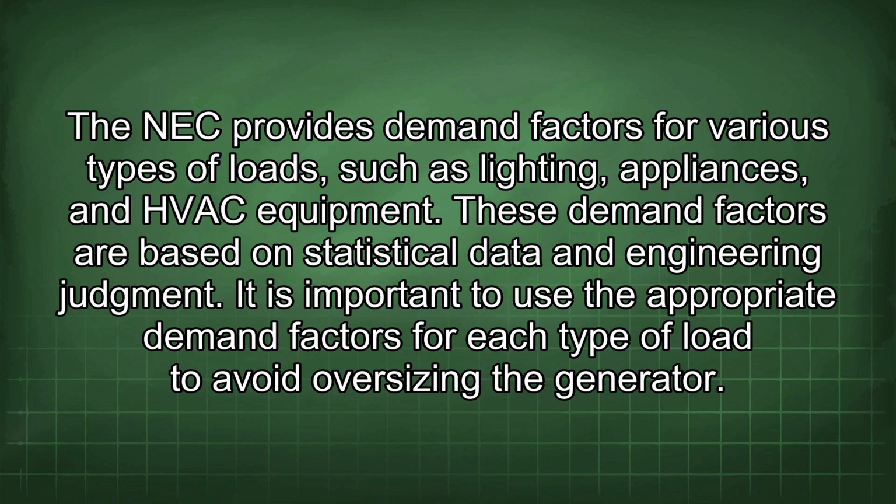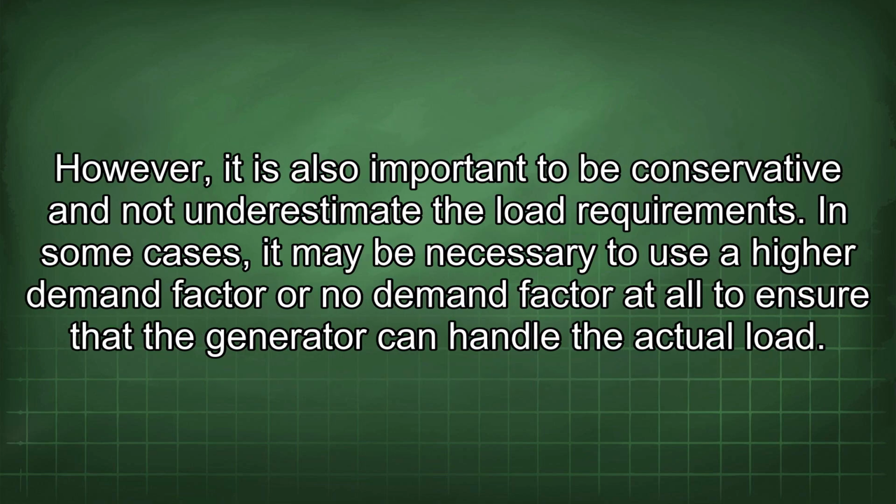It is important to use the appropriate demand factors for each type of load to avoid oversizing the generator. However, it is also important to be conservative and not underestimate the load requirement. In some cases, it may be necessary to use a higher demand factor or no demand factor at all to ensure that the generator can handle the actual load.